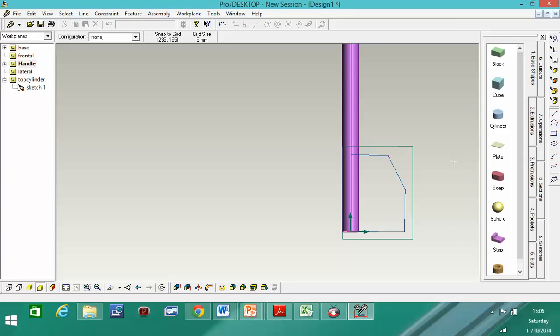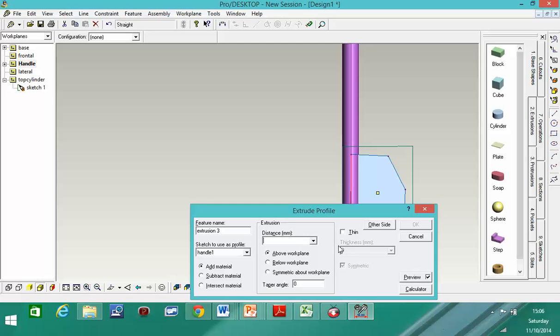Okay, what we need to do now is to make sure that we can extrude this. Let's make sure that this shape is closed right now. As you can see now that this surface turned into a kind of sky blue. Alright, let's extrude this to give this a certain thickness, add material, and then say we want a handle to be about, say 20, or say 50 mil, a bit thick. All right, 5 centimeters. How is it? Is it too big? Say 40.